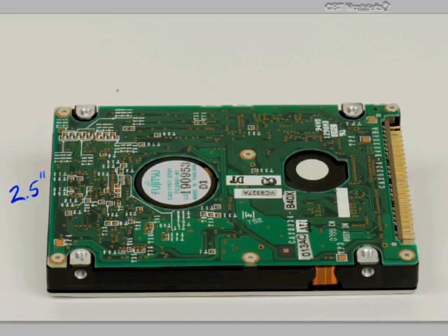This refers to the actual round platters themselves inside of the hard drives. Those are 2.5 inches, whereas a desktop PC hard drive would be 3.5 inches. Okay, so there's a little bit of difference in size right there. Also, the connectors themselves here are going to be different on a laptop, because you'll see that these are going to be cropped a little bit closer together. You can't take a desktop connector and fit them on there. It'll be too wide, but they're specially designated and sized for a connector inside of a laptop.